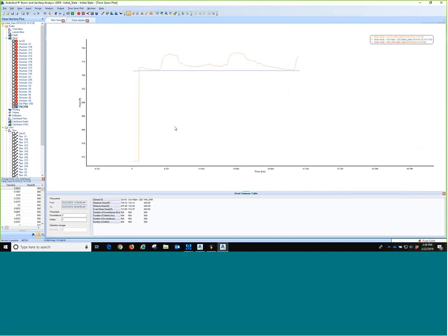Okay. Oh, where are you, wet well? Down here somewhere. Point is, I can see my elevation right here. This is the elevation of my outfall, right? 710. Up here, where I had my peak outflow of 63 gallons per minute, says my head is 718.